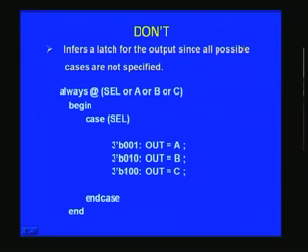What will happen in this case, because this is not specified and there is not even a directive, it simply infers, this tool will infer that this is a latch. That means to say, let us say it has passed through for a particular condition, and it has previously stored B. Although this is a combinational circuit, it may ultimately be used in a sequential circuit wherein you may register, but still here also it does matter. And what will happen?